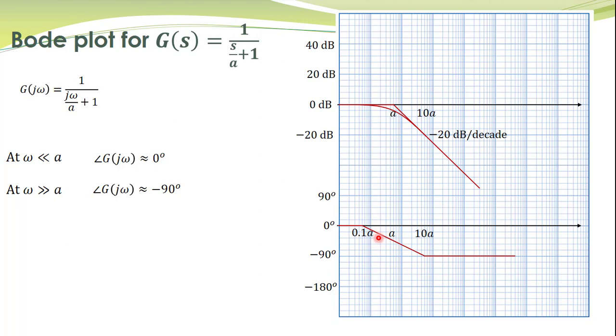Just like we have manipulated root locus, we already knew the effect of adding poles and zeros to the root locus and how it will be affected by those poles and zeros, and therefore we easily reshaped the root locus. Similarly, over here, once we know the effect of adding poles and zeros to this Bode diagram, we shall be able to reshape these Bode diagrams and therefore design controllers for systems. So in the next lecture, we shall talk about Bode diagrams for a few more transfer functions a little bit more complex than this one.